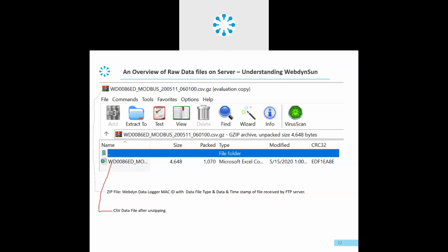So it depends on how often you want to collect the data and how you want to push the data to the servers. Normally, we see that the data acquisition is 15 minutes and the data connection is 15 minutes in most cases at solar levels. Static IP is necessary.